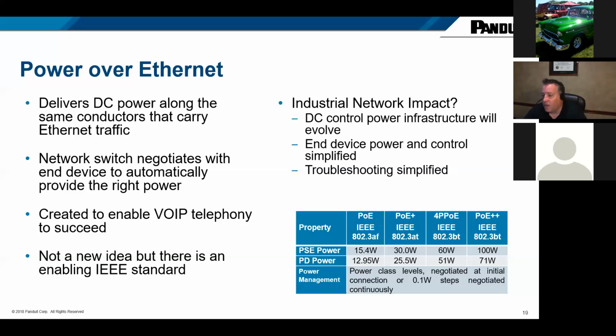What I will say from an infrastructure standpoint is when you deliver power over Ethernet, you've got heat. And so the IEEE doesn't require it, you can do PoE on Cat 5e, but they recommend Cat 6a cabling for PoE. And really that's because of the heat rise and the ability for Cat 6a to dissipate the heat. When you're doing a lighting project, you're going to have bundles of PoE cables, and the cables in the center are going to heat up pretty hot relative to the performance, and that can degrade performance. So we actually have white papers on how to build this out properly, and I think there's a link at the end.